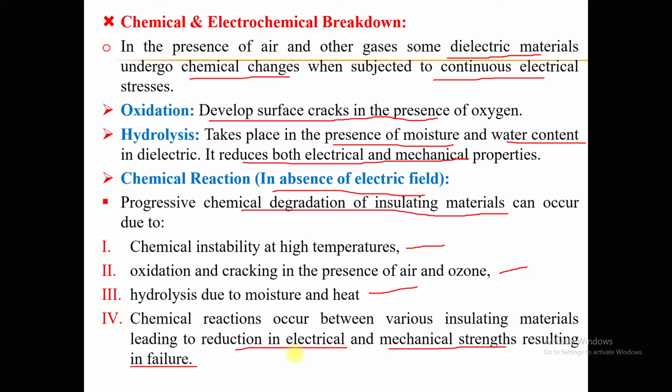The oxidation process is normally observed if gas content is found, for example if oxygen is present. The hydrolysis process is usually found if the solid dielectric contains moisture or water content. Because of imperfections, this kind of phenomenon is normally seen at prolonged operation of solid dielectrics.